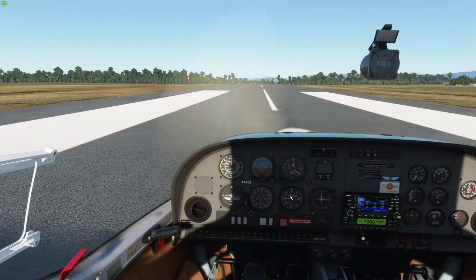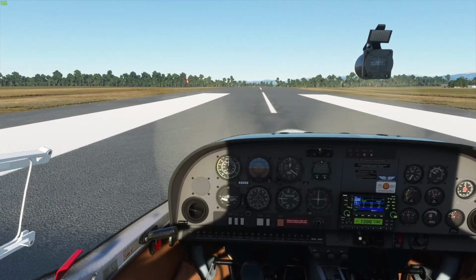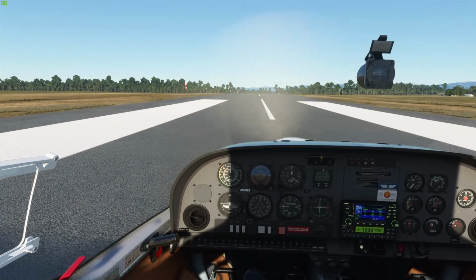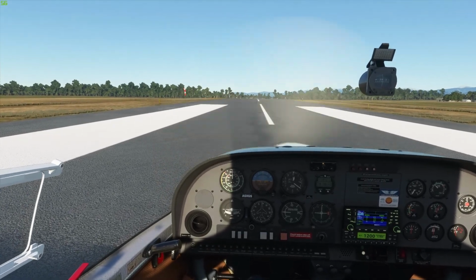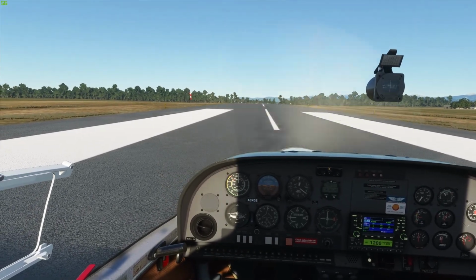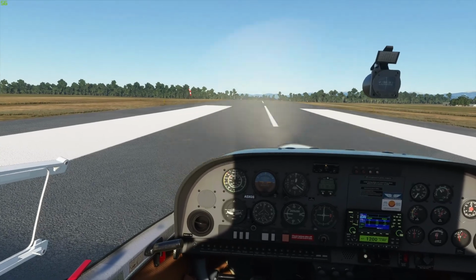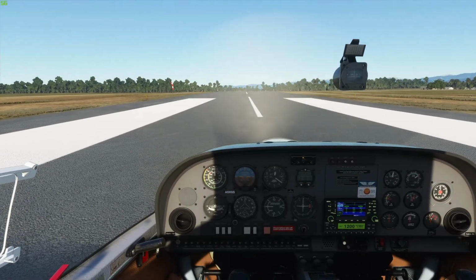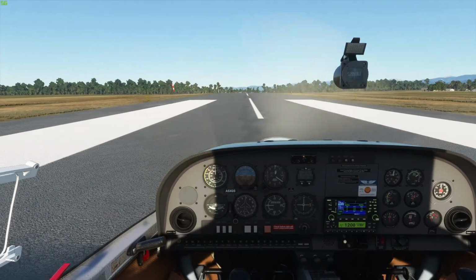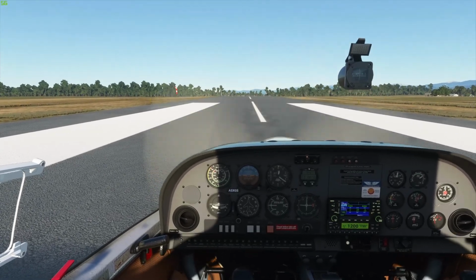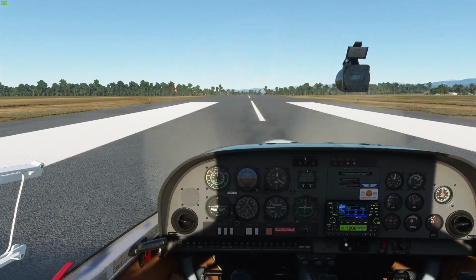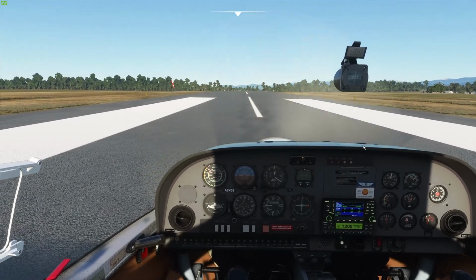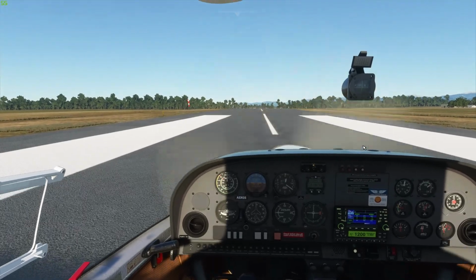Alright, here we go. So as I mentioned, I'll just be looking for somewhere between 50 and 60 knots. It may want to fly earlier than that because I suspect it probably will because it's quite a light aircraft, but the idea is we want to be well above the stall speed anyway. So I'll just bring the power up on the brakes. So that's full power. So I'm getting 2,500 RPM and about 30 inches of manifold pressure. The temperatures and pressures are in the green, so the engine's good. Brakes are released.